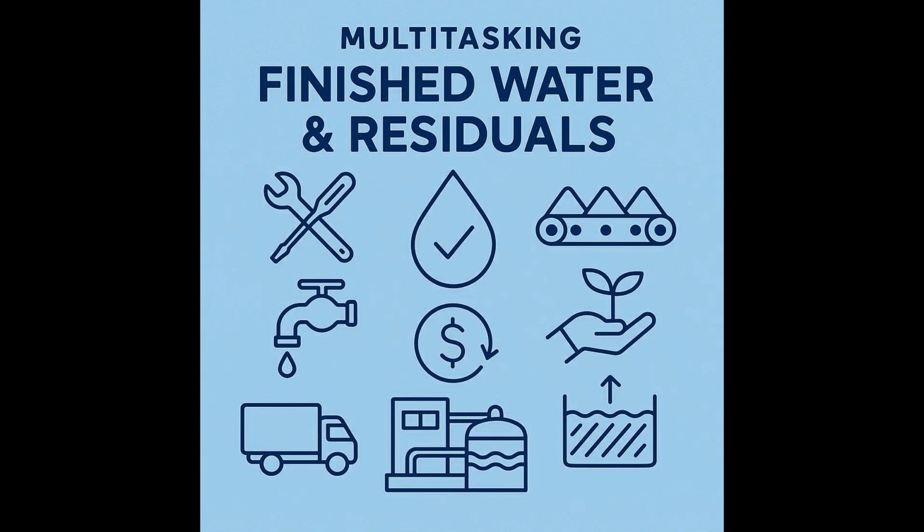Okay, so let's unpack this then. Residuals, it sounds a bit vague, like leftover dinner or something. What exactly are they in this context? Yeah, it sounds vague, but believe me, to a plant operator, it's anything but. In drinking water treatment, residuals are simply the byproducts, the waste streams generated when you take raw water from a river or lake and treat it to meet those really strict finished water standards. Think of it as everything that was in the raw water originally, plus some of the treatment chemicals maybe that we definitely don't want ending up in your drinking glass.